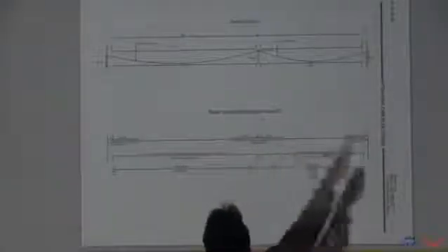One thing that students sometimes are frustrated on is if I tell it, calculate the force and profile, it's going to fully drape the system. And it's going to try to drop off tendons, and it's going to fully drape both bays and then give me the least amount of force it can in each bay. It's a design program. It's trying to come up with the most efficient, cost-effective design. So if you leave and you bounce around and you look at different things in the program, and then you come back, it's going to try to redesign you. It's going to think you changed something, and now its job is to come in and give you a really good starting point for design.